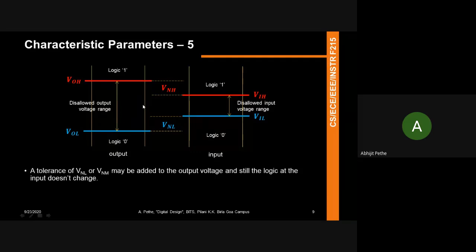Sahaj asks, can current flow through the gate backwards? I don't know, what do you mean by backwards? A direction which is not intended, like through an AND gate, but backward. If you look at the circuit design, it can flow, but that will be a wrong operation. You don't want your gate to do that. Normally the currents flow in the same direction as was intended in that diagram. That's why you have IIL and IOL, or IIH and IOH. You don't want the current to flip direction, which would mean it has gone from high to low.